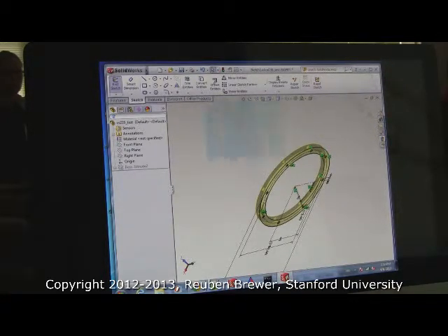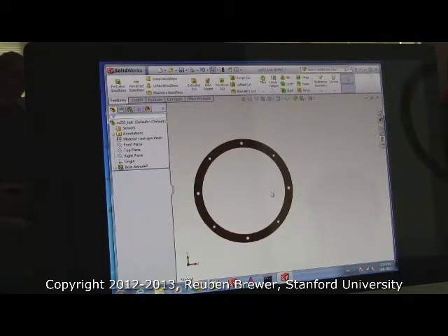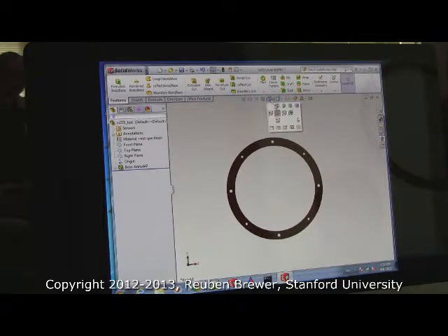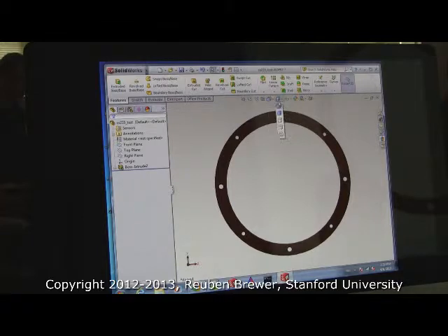So the way you get back is you see right here, this little icon gives you all of the different orthographic and isometric and normal views that you could possibly want. This button here is really important. That arrow is normal to a plane. So press that and see how your sketch now is easily modifiable. Everybody got that? Okay, cool. So go ahead and just hit the purple mark. Yep. Play with those buttons. Go ahead and go through each of them so you can see it rotates you to different planes and faces.